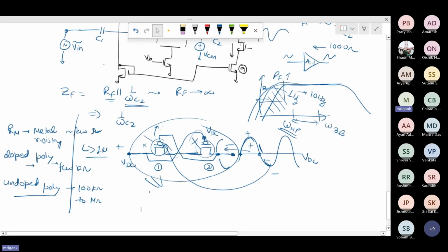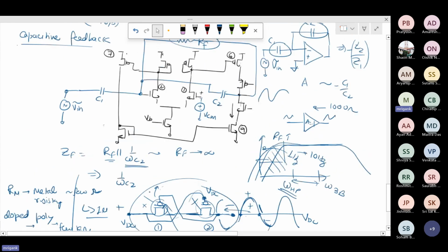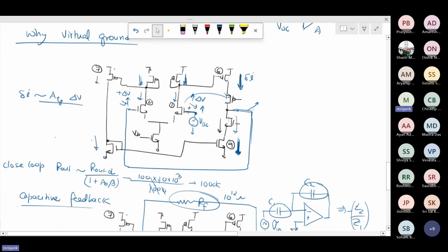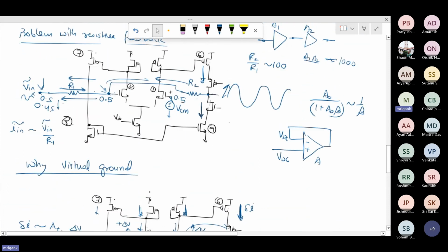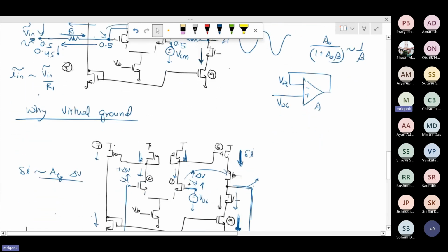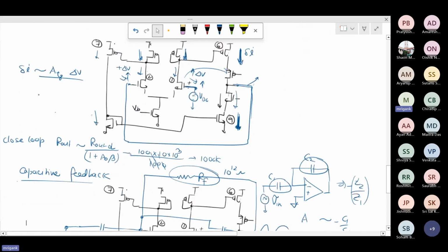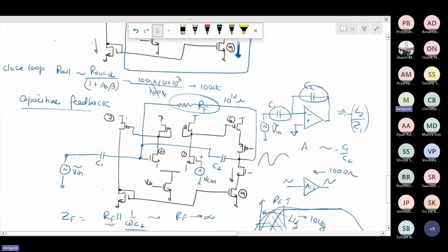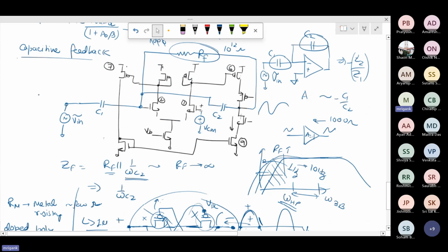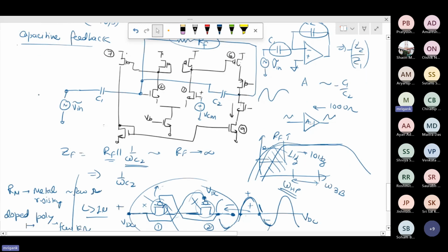Any question? I've already described the assignment to you, so those who are present can carry out the 3 steps. First is connecting the resistive feedback and trying to see the effect of the mismatch in the DC between VCM and the input DC, and see how the output value is affected. Second, using the ideal resistor RF and capacitive feedback, apply the AC signal and get the gain. And third, you can vary the RF and see how the cutoff frequency changes, and then try to implement that RF using this.